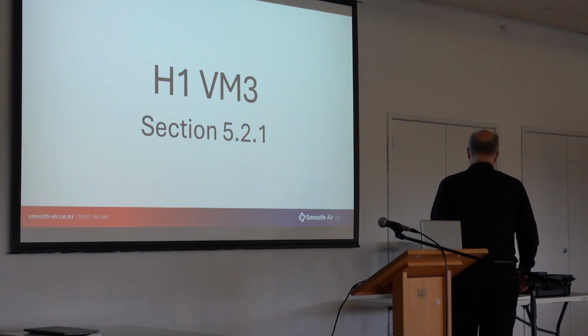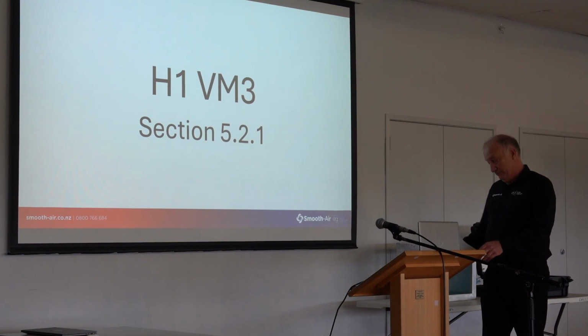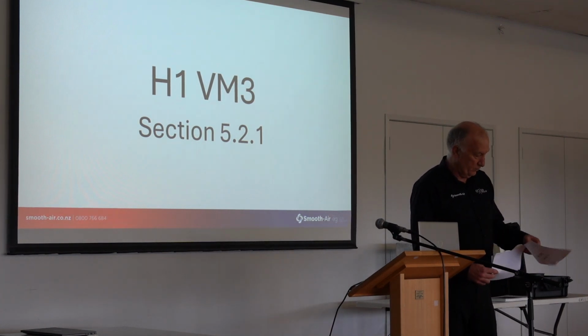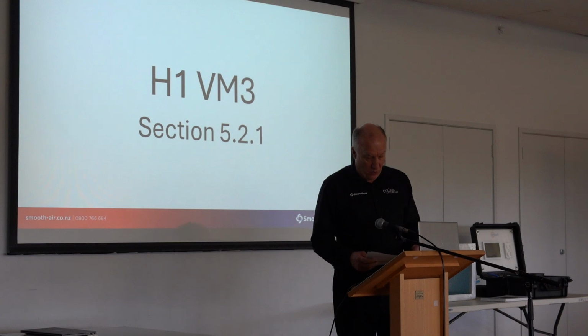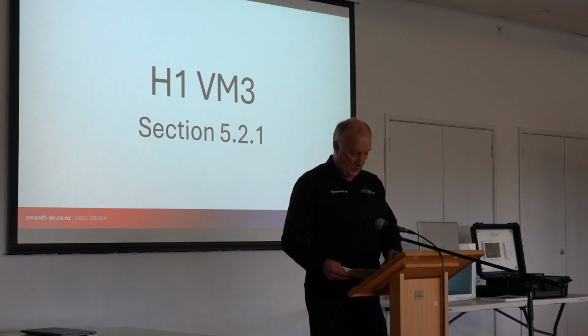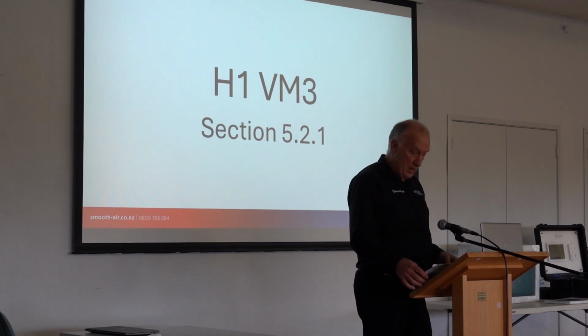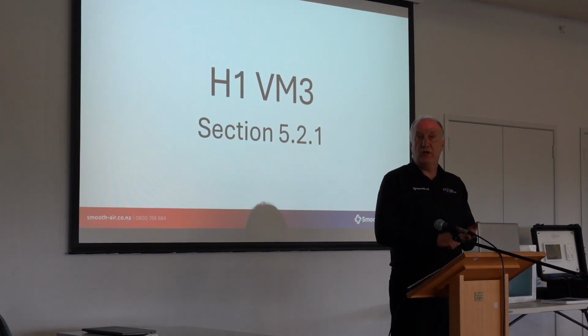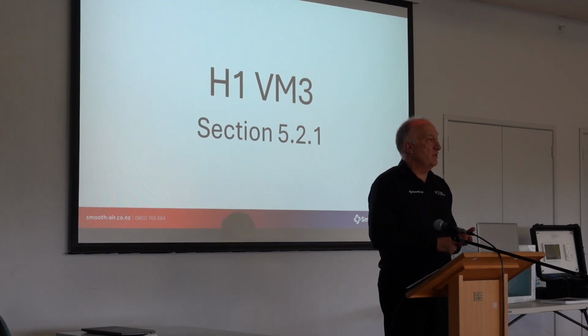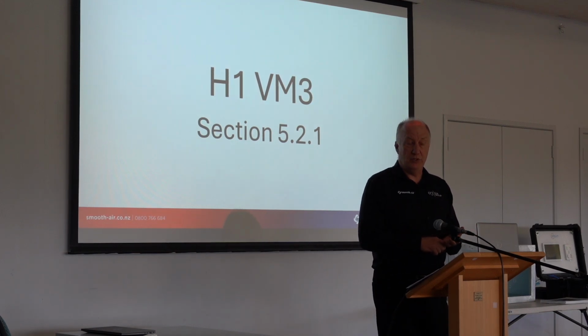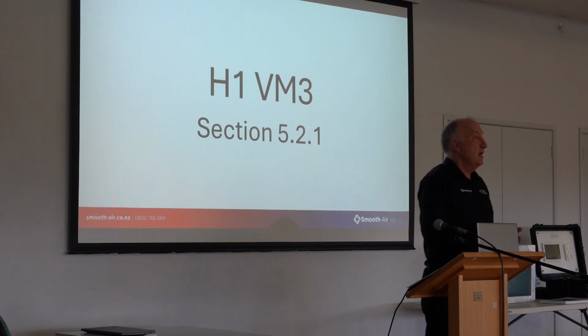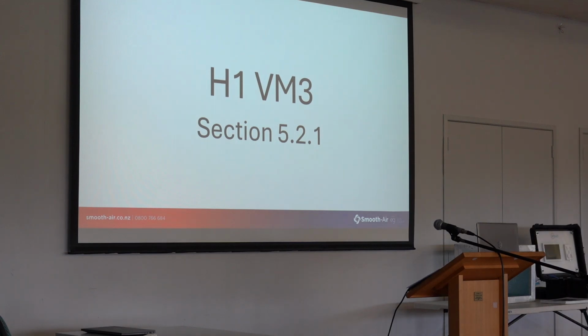So, notes, because I'm no expert either. Some notes on 5.2.1. It's a pretty dry topic, to be fair, so 7 minutes is probably enough. It was implemented in November 2021, so if you're doing a commercial building that's got a new consent at that time, you need to comply with it, if it's a commercial building over 300 square metres. In terms of insulation of duct, the flex is really easy. You've got to be R1. Most people can comply with that.